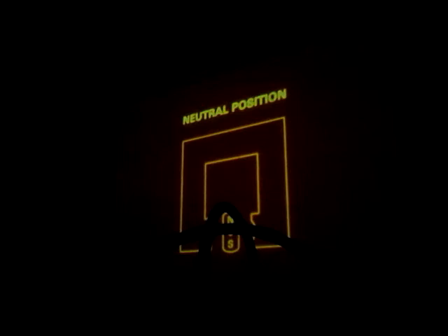Now, as this magnet rotates 90 degrees from full register, it is said to be in its neutral position, preventing the flux from flowing in the frame. The primary winding of the coil is actually wound around the magneto frame. So, as the magnet inside rotates, the flux will change, inducing a voltage into this winding. This causes the primary current to flow.